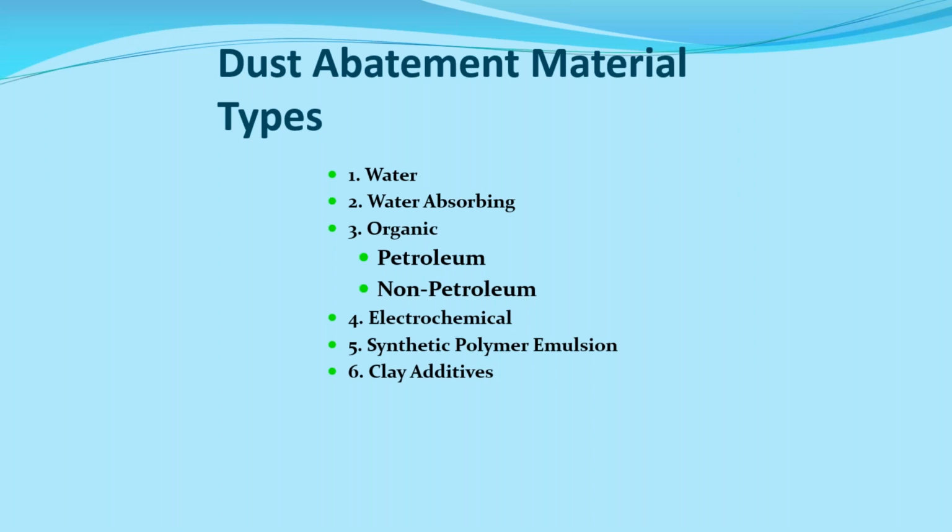And then the final item that I have there is actually an additive that, you know, in some parts here in the state of Idaho, we have a lot of basalt, a lot of lava rock. And in those areas that we have a lot of lava rock and not very much borrow, we actually quarry the lava rock and crush it. And then we have to add a clay additive to bring the PI up on our roadway to try and hold our roadway together. And so these are the 6 areas that we're going to be talking about pretty much for the next hour, okay?